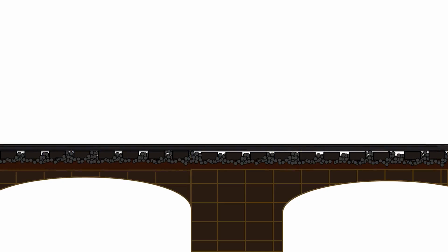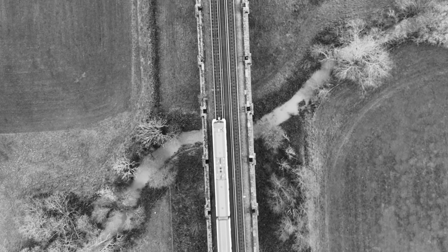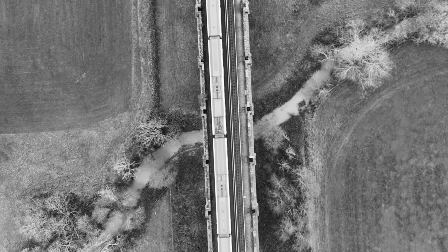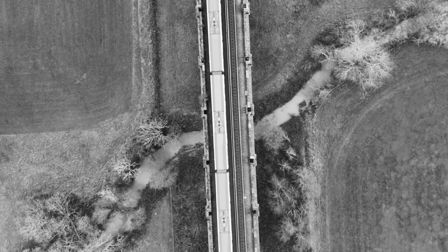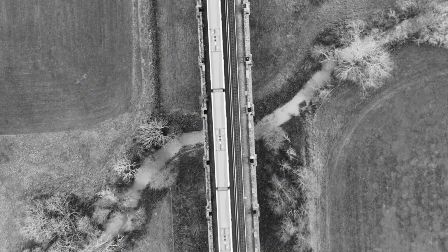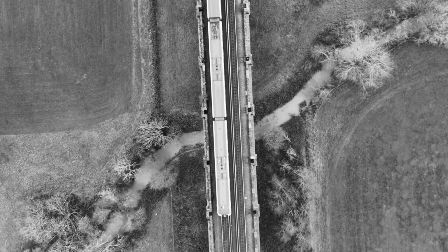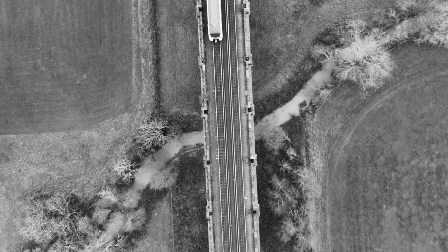The track often sits on fill above the arches, but that fill holds moisture. Over time, this causes degradation, which leads to drainage issues and uneven support for the track above. The parapet walls down the side often have to be held in place by steel tie bars. Modern trains generate lateral loads far beyond what the Victorians could ever have imagined. Combined with a track lift and increased ballast loading during renewal activities, this can add significant outward pressure.